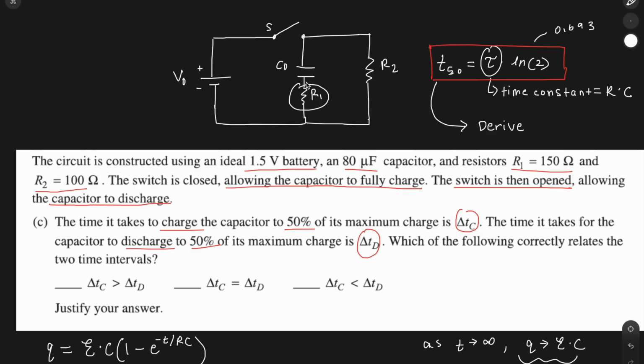However, once we start discharging the circuit, we remove the battery entirely, and we just have our connection between our capacitor and our two resistors. So in our new system, the equivalent resistance is that of a series resistor system, and in a series resistor system, our equivalent resistance is going to be R1 plus R2 for our discharging. That is the key difference between the equations we obtained.